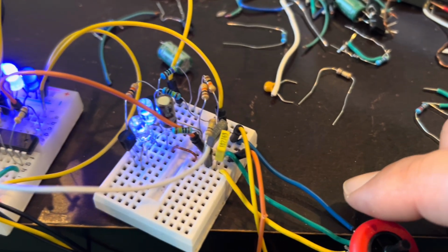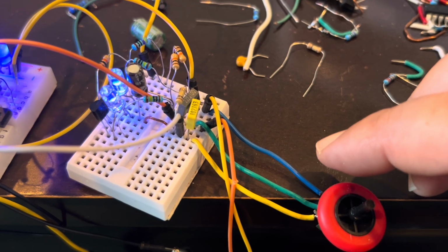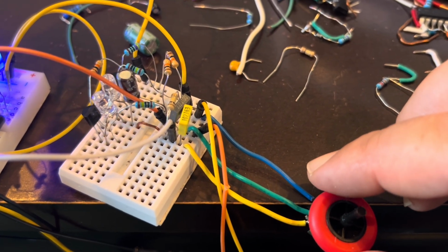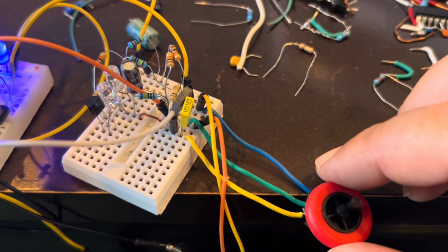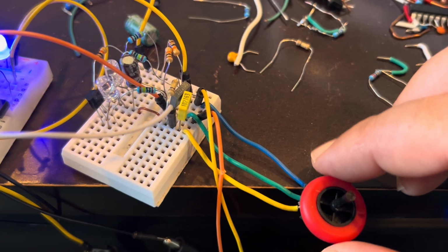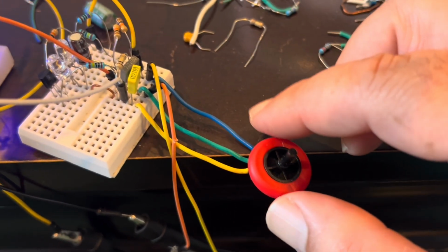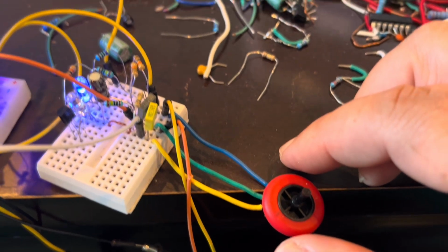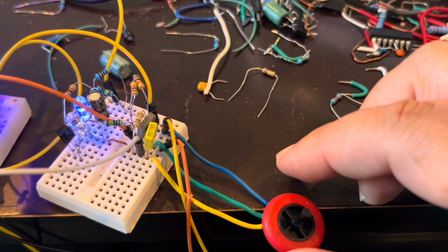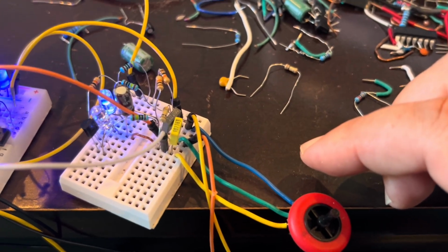So what I accomplish with that, so let's say I'm turning this clockwise, A goes on first, right? So if A goes on first, let me get it to just A lit up, it's very sensitive. So A is lit up here, so that's the data. That's a 1, a logic level high, 5 volts here.